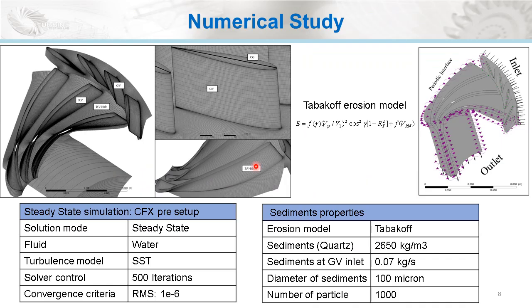For conducting the numerical study, the turbine of Jhimruk hydropower plant with 24 guide vanes and 17 runner blades was used. In order to minimize the computational time period, passage modeling technique with the 3 runner vanes and 4 guide vanes is considered in all the simulations.